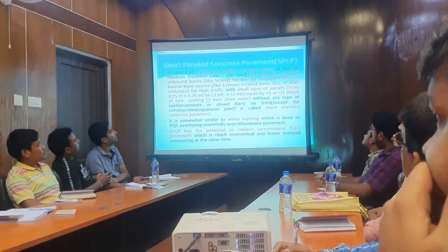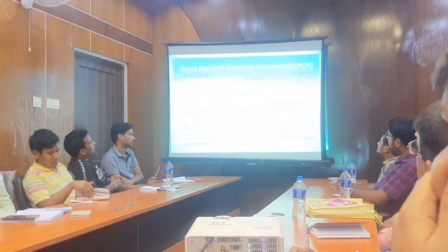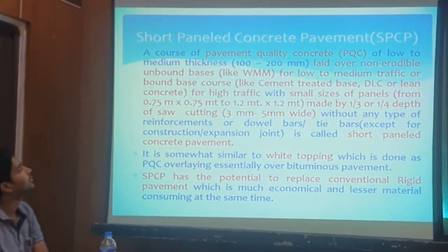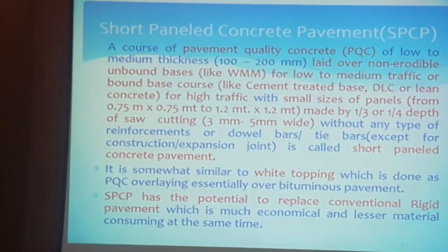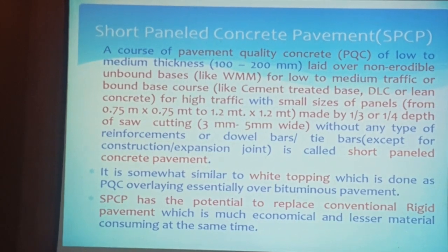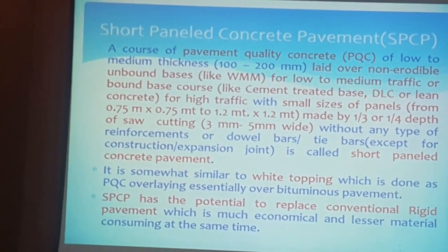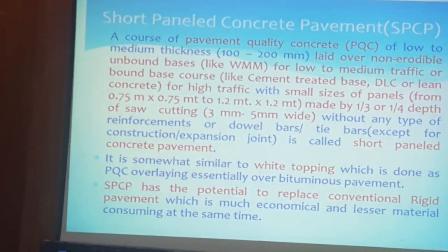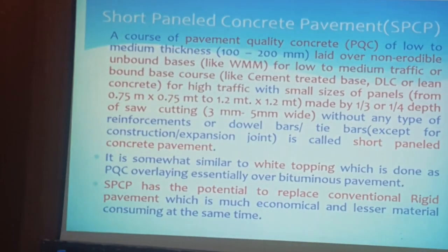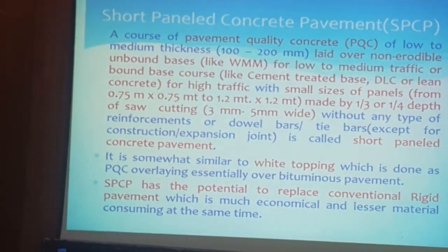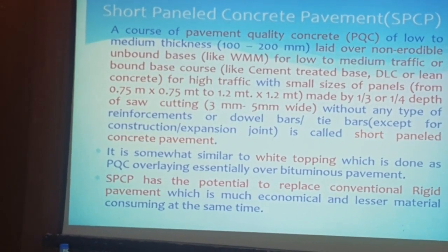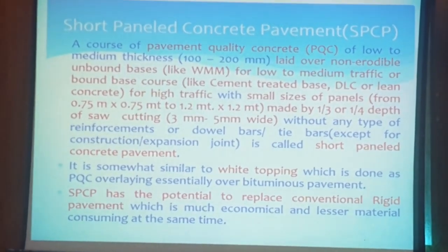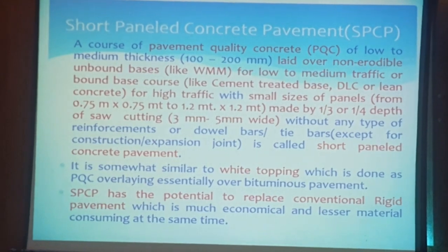It's very near relative to white topping. That is short panel concrete pavement. Short panel concrete pavement is also the same thing, on a non-bituminous base. If the concrete overlay is done with a much lesser thickness than your conventional PQC, with some shorter panels made by saw cutting to 1/3 or 1/4 depth, that is short panel concrete pavement.